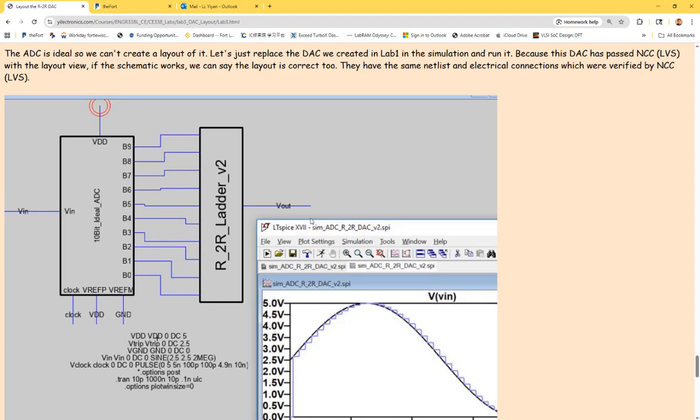And we do DRC check with this sub-module, even LVS as well. We create a sub-module, we create a layout version of the sub-module. It's done in the library. And then we do an LVS, we do DRC, both are clean, okay? We know this guy is safe to use.